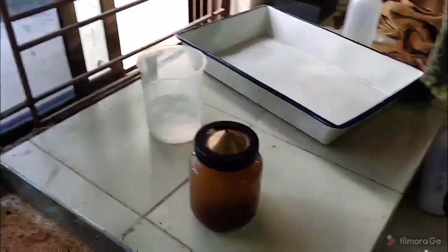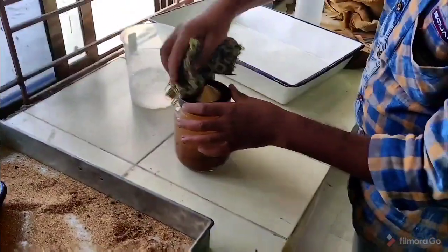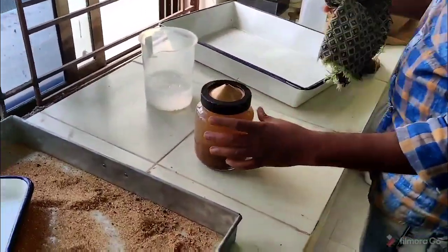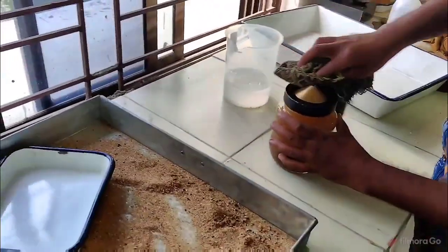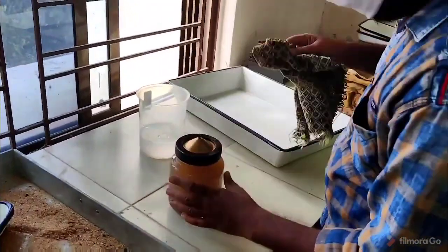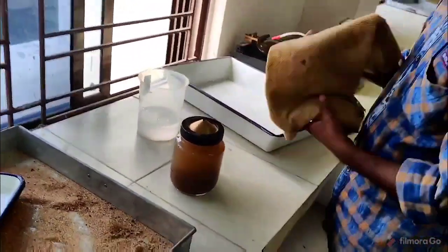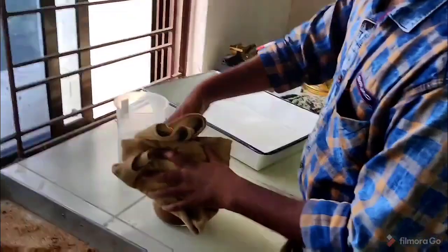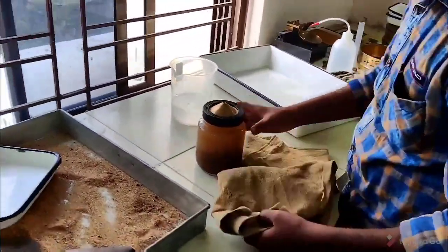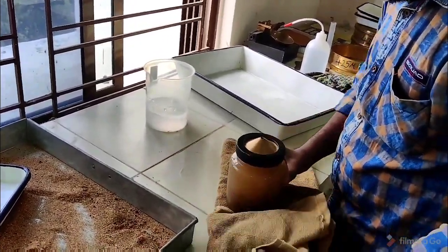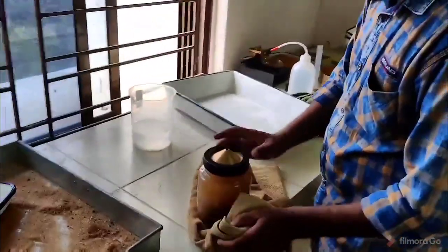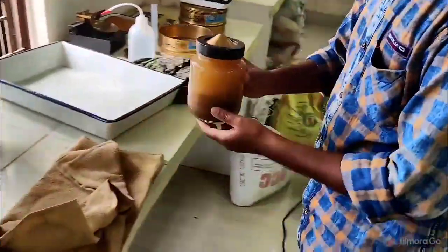Now wipe again. These are the minor major precautions we should take during the experiment because it can alter the results. Okay, now the pycnometer has soil sample of 500 grams and the rest of the space is filled up with distilled water. So we will take the weight of this pycnometer having sample plus distilled water and note down the weight in our tabulation. Take the weight.